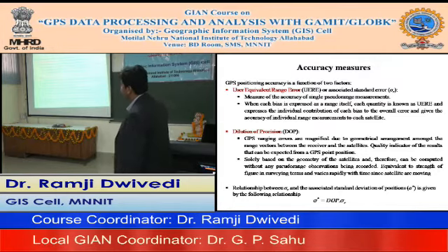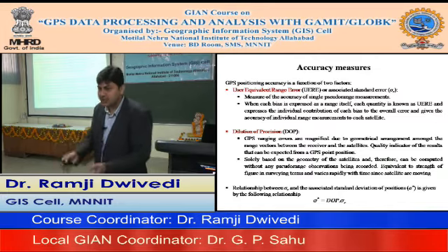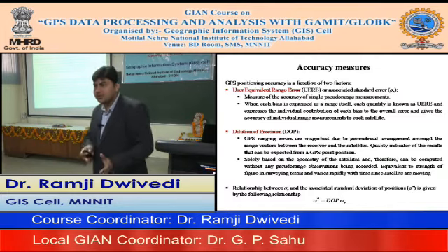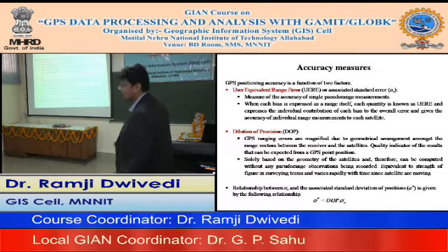The word says dilution of precision. We could also understand it as dilution of precision in the final estimates. The more you are prone to errors, the more the dilution, just like concentrated and diluted acids. It is totally based on the geometry of the satellites, how you are looking at them, and can therefore be computed without any pseudorange observation being recorded. It is equivalent to the strength of figure in surveying terms.